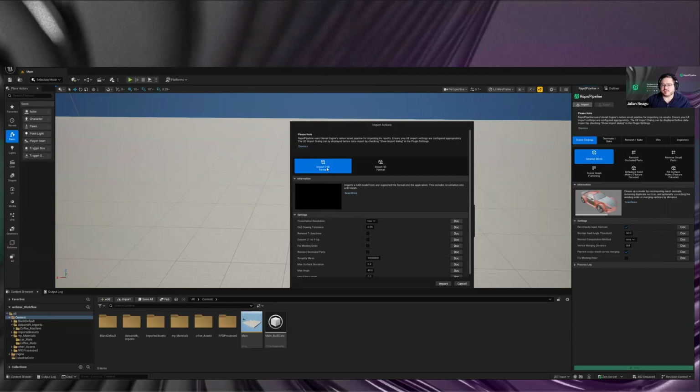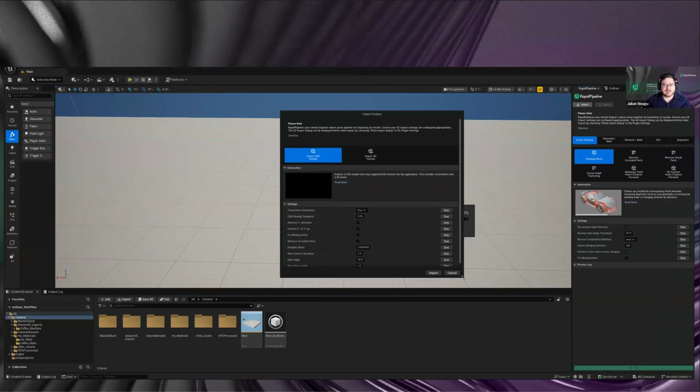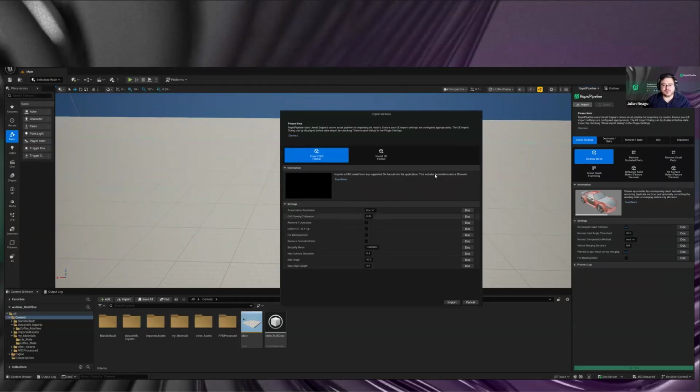But default settings, exactly. But basically, to fine-tune and steer your import process, of course, you can then go into, if you have a CAD file like I have right now, and dive a little bit deeper. So we have some of these presets, all of the presets I went through before. So from extra coarse to extra fine. But then you also have the custom option where you can then fine-tune the tessellation of the CAD file. And we also have a detailed documentation about what these values mean and how you can fine-tune this to your liking.